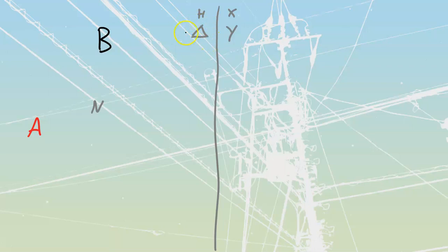Okay, my high side is a delta, which doesn't actually have a neutral. The neutral just exists in the very middle, and all the voltages are automatically balanced around it. So we can draw out our third missing line over here, C, and now we can make our connections. As with everything else, once again, H1s are going to be associated with the actual proper lines.